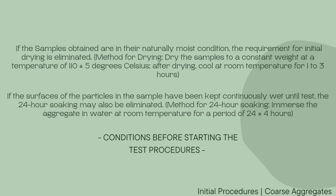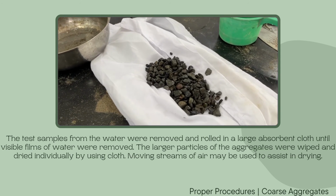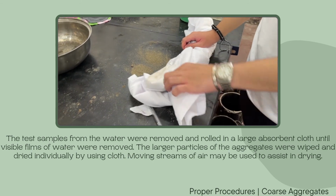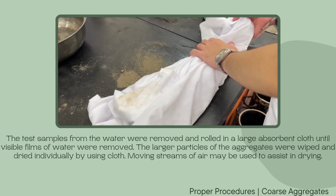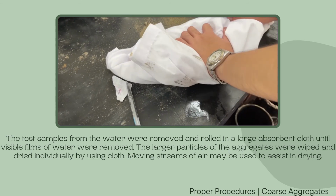If the surface of the particles in the sample has been kept continuously wet until the test, the 24-hour soaking may also be eliminated. Method for 24-hour soaking: immerse the aggregate in water at room temperature for a period of 24 plus or minus 4 hours. Number 2. The test samples were removed from the water and rolled in a large absorbent cloth until visible films of water were removed. The larger particles of the aggregates were wiped and dried individually using a cloth. Moving streams of air may be used to assist in drying.